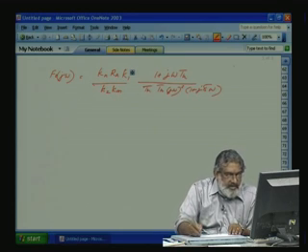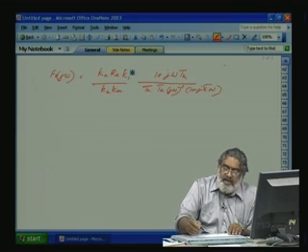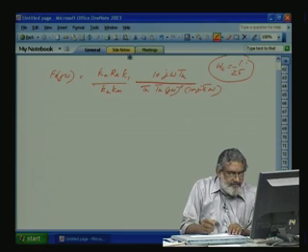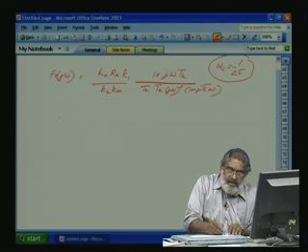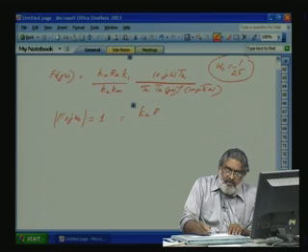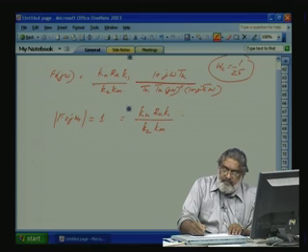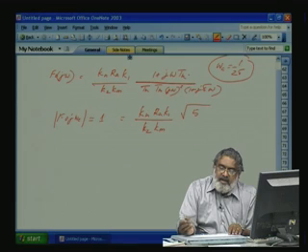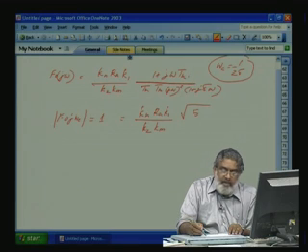Now, we know that at omega c, Tn is equal to 4 delta, and omega c is equal to 1 by 2 delta, that we derived last time. So, substituting this, F0 j omega c should be 1. That will be equal to Kn into Ra K1 by K2 Km into root 5, that is the modulus we are taking, Tn is equal to 4 delta.